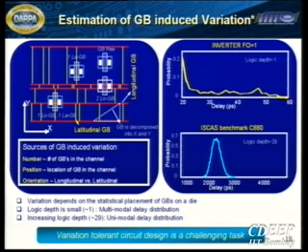And at the end of it, I have to also worry about, is it a longitudinal grain boundary or a latitudinal grain boundary? Now, of course, there are process technologies where I can possibly have grain boundaries only in one direction, and that's possible. So what we did is we looked at the possibilities of how much of a variation I am going to have on some of these benchmark circuits. We looked at an inverter with a fan out of 1 versus some of these ISCAS benchmark circuits, and in this particular case, this particular one had a good amount of variation.